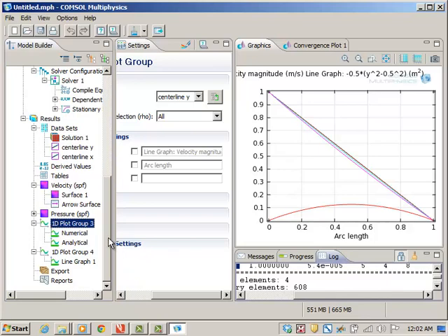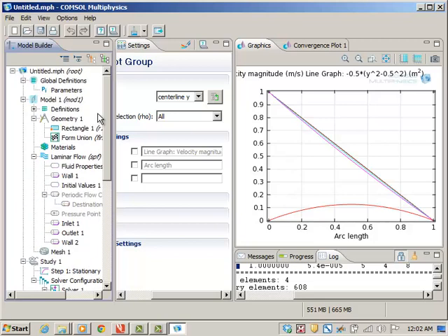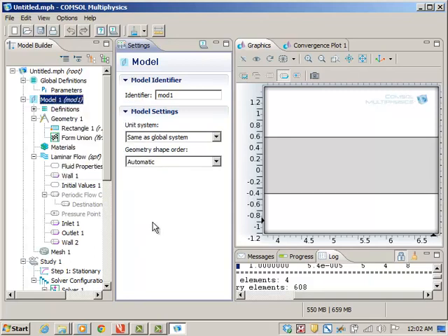So we can use this to model this fluid flow. And once you get this basic idea and start building these basic models, then you can add multiple physics by again right clicking this, and then you can add mass transfer and heat transfer to this flow problem and solve a fully coupled problem. So let me save this model, and let us move on to the